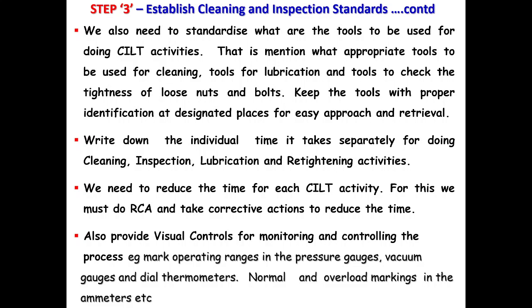Also provide visual controls wherever possible for monitoring and controlling the process and production. Example: mark operating regions in the pressure gauges, vacuum gauges and dial thermometers, and normal and overload markings in the ammeters.